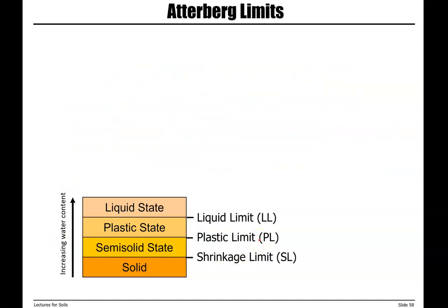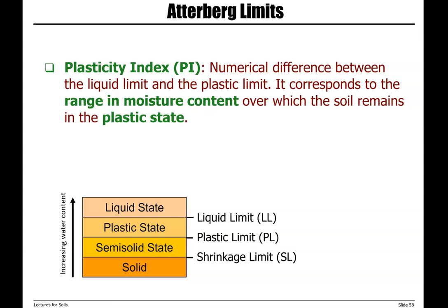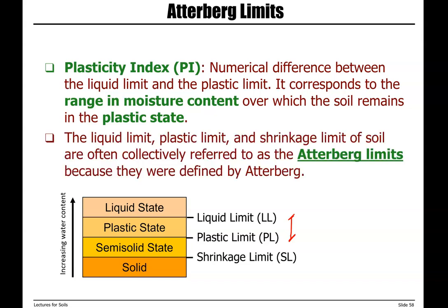Another parameter that's important for us is plasticity index. So what is the range within which soil has a plastic state? This is called plasticity index or PI.